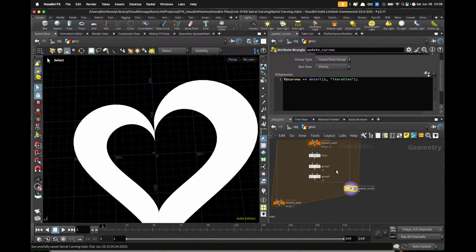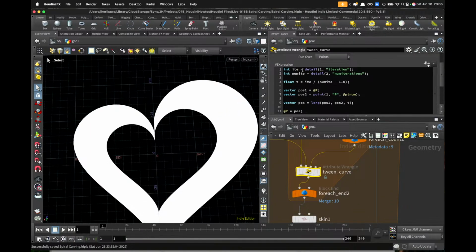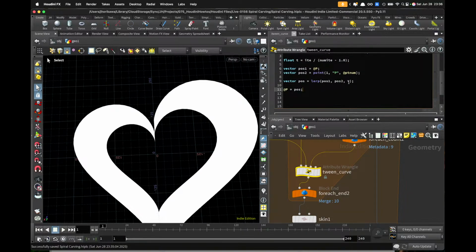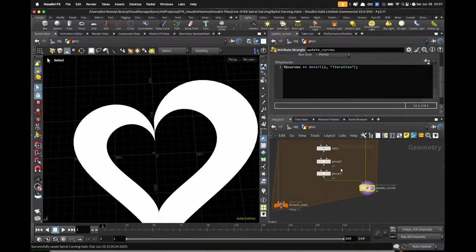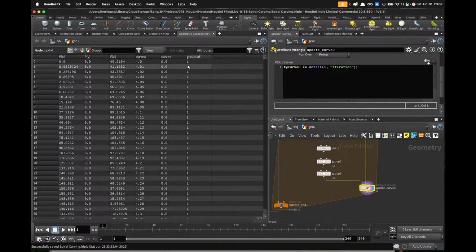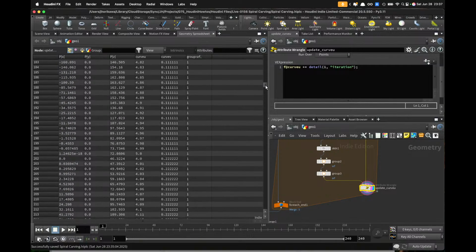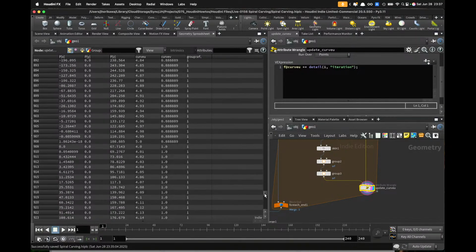So you can apply that inside this tween curve, which you just need to have this t information applied to this perpendicular direction. Let's call this curve V. Okay, and if I check it, you have curve V from 0 to 1.